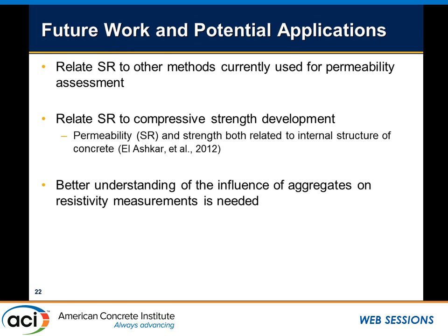And finally, a better understanding of the influence of the aggregates themselves is definitely needed, because we are starting to do some work right now where we looked at different types of aggregate sources, and we found that while the correlations are the same and you get more or less the same behavior, there's a pronounced effect when you change from one aggregate source to another, what your resistivity values actually are.